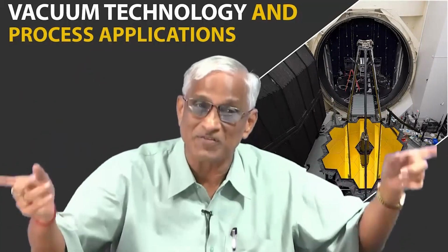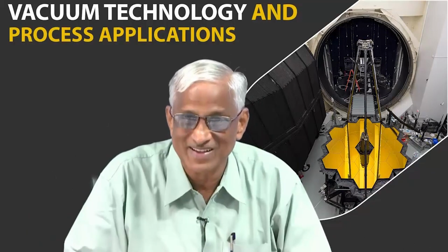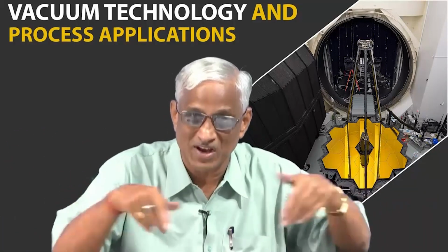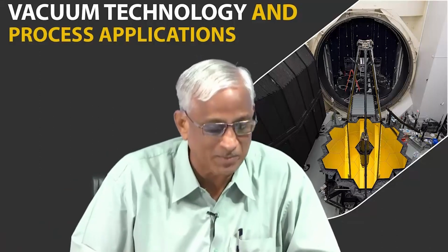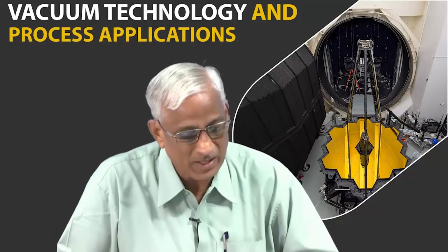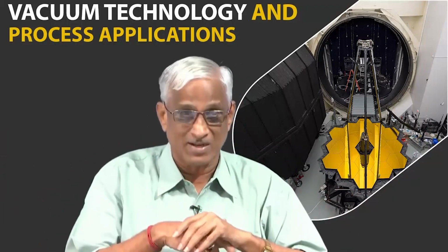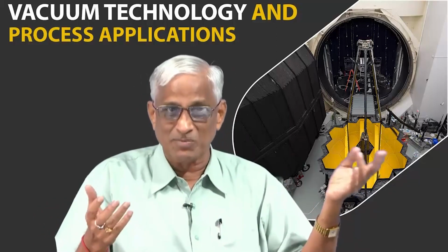That means coating for coating applications, but this coating is a passivation coating, so that foreign molecules will not interfere with your thin film deposition or plasma deposition or electron beam deposition, which we will see later in the applications. Okay. And these coatings can be developed by the same methods which we use for thin film depositions in the semiconductor industry, like sputtering or physical vapor deposition or electron beam or ion beam.